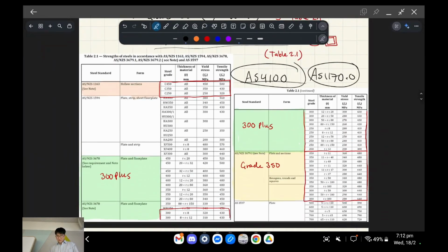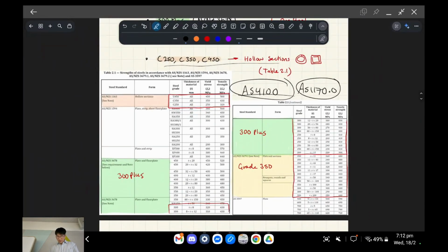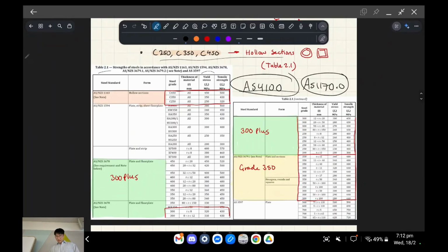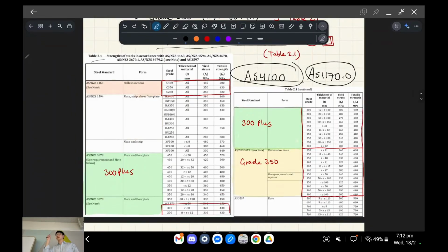Okay. So in table 2.1 of the standards, we basically have different descriptions of yield strength, yield stress, sorry. And you follow the table, and it's based on thickness, right? So generally the rule is the thicker a bit of material is, the lower its yield strength is, and the thinner, the higher its yield strength is. Does anyone want to have a stab at why that is?